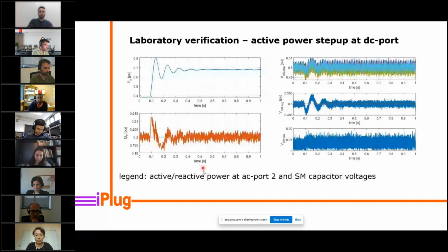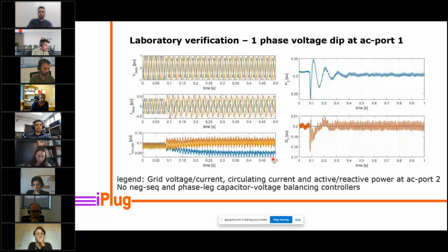We could see that when we deal with multi-level converters, as you all know, the most important factor to keep an eye on is keeping the energy or the capacitor voltage at a decent level. The average capacitor voltage is like this, which means it always sees a low dynamics when there's a power transfer, but they are balanced, and it seems to work.